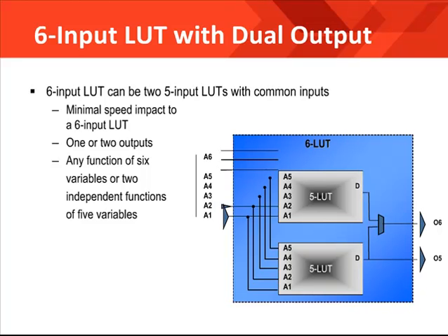Every customer must understand the input limiting nature of LUTs because many customers are used to building with ASICs. It is important to understand that the HDL code you write needs to be optimal for the FPGA. This is because ASICs are faster than FPGAs, and it's much easier to get good speed from an ASIC with suboptimal HDL coding styles.